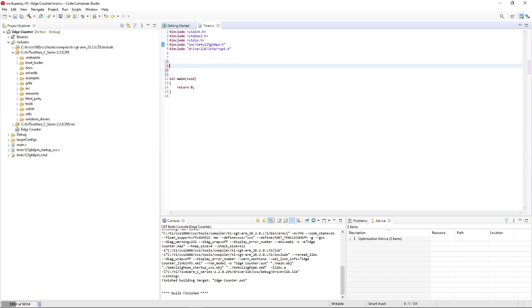And the way that we're going to do this is we're going to have the photoresistors in a line, essentially, and we're going to count how many of them are blocked at certain intervals based on feedback that we get from the conveyor belt itself. So obviously the first thing we need to do is write a system that's capable of counting something, anything, based on some external information through an interrupt.